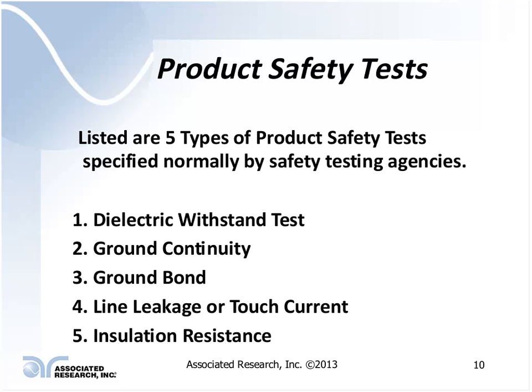Okay. And lastly, an insulation resistance test. This is a test to verify the integrity of the insulation within the product itself. And this is similar to a dielectric withstand test, but it's typically done at a lower potential. It's commonly done as a maintenance test in many types of products.